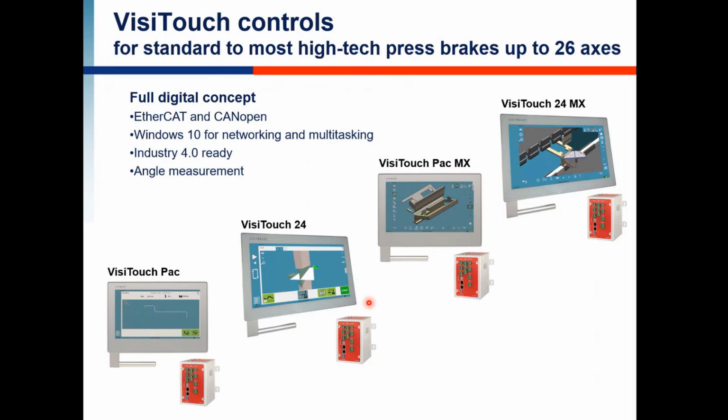The main advantage of VisiTouch will be the EtherCAT and CANopen compatibilities with a lot of different drive manufacturers. So only one wire connected to all the drives. You don't need to wire everything, all the digital inputs, you don't need to wire the encoder inputs, the analog outputs to manage drives. It runs on Windows 10, so you can put it on the network, you put a keyboard, mouse, and so on. We have Industry 4.0, that is a plugin and an option to install.